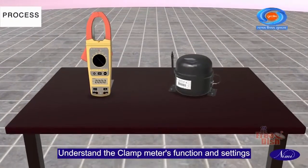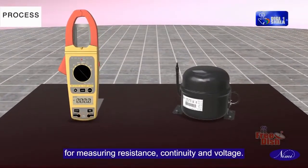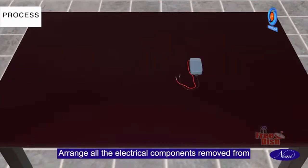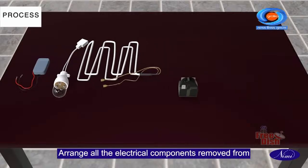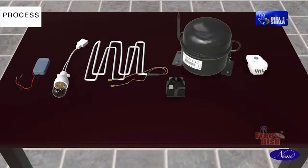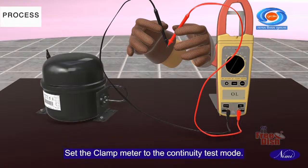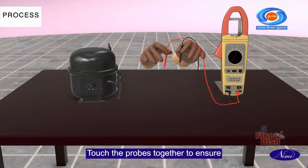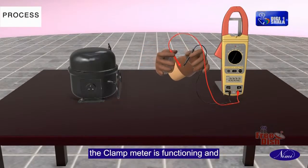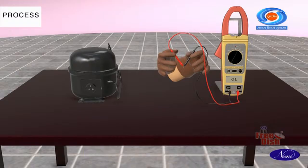Understand the clamp meter's function and settings for measuring resistance, continuity, and voltage. Arrange all the electrical components removed from the refrigerator in a clean and organized workspace. Set the clamp meter to the continuity test mode. Touch the probes together to ensure the clamp meter is functioning and emits a sound or indicates continuity.